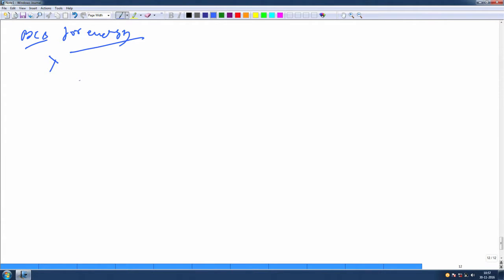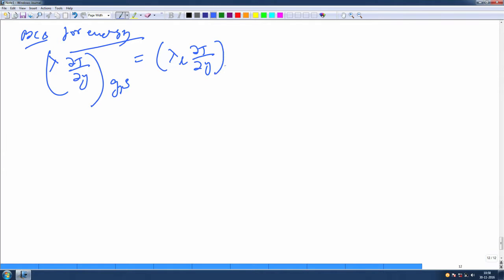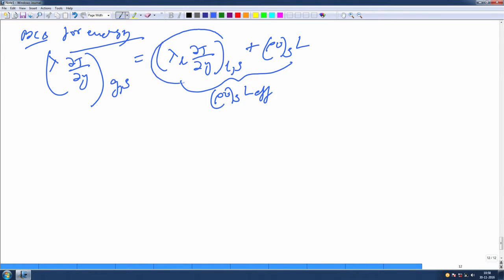So, once again, if you recall what the energy equation was, it is the flux at the gas side of the interface, then this is basically on the liquid side of the interface, right, plus there was this rho Vs which was basically the mass flux into the latent heat. Do you recall? That was the latent heat, right, and sometimes we wrote it as rho Vs into L effective. Is not that so, right? And then we had a lot of argument regarding the nature of this. This is basically that conduction heat flux, right?